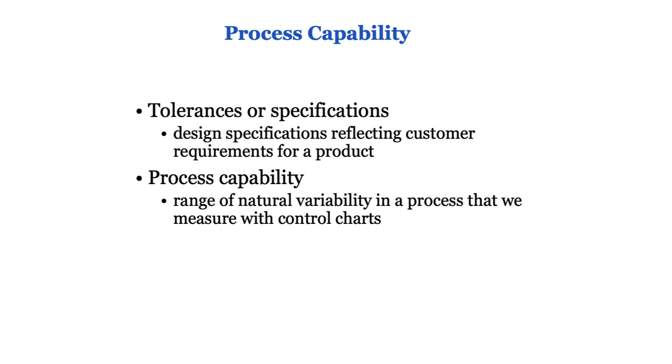If an operator finds that a sample characteristic, mean or range, does not fall within the control limits, he or she should immediately stop the process, determine the reason, and perhaps take remedial action to bring the process back in control. Control limits do not tell us whether a process is good or bad, only whether it continues to operate as it was in the past.